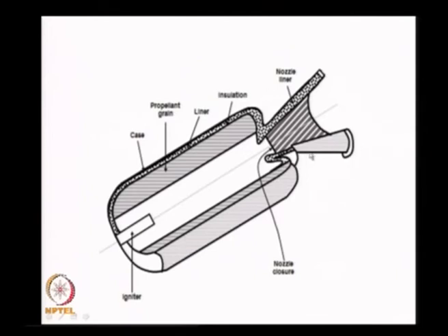What are the components of a solid propellant rocket? Well, propellant, basic. It is contained in an insulation or a liner. Then after this insulation I have another liner. Make sure that it is compatible with this insulation such that when the motor burns, the heat does not allow the motor case, which is metal, to burn off. Therefore I have a propellant, I have a case, I have insulation, and liner is also a form of insulation. And then I have this as a nozzle.